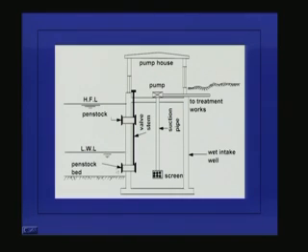So, we have two different pipes here which can draw water from the river to the intake structure, that is a high level penstock and a low level penstock, and there is a screen here at the front of the penstock. This screen is preventing the debris from entering into the intake structure or entering into the treatment works. There is a pump here, the suction pipe of the pump is like this, and this is the screen here which is again